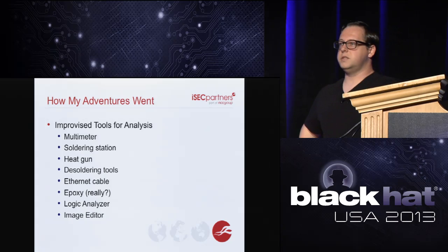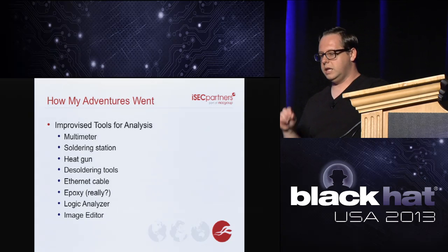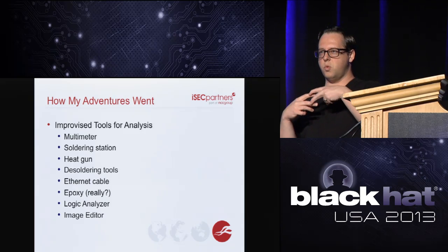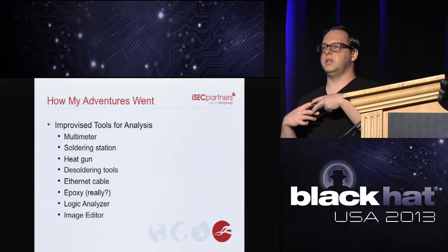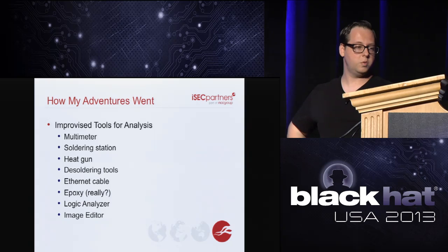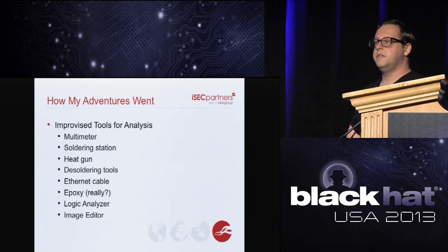The other thing it can do is, if you have really small leads and you want to get some wires on there, if you're just right and you put enough pressure on, you can push the wires on and glue them together. So you can actually glue the wires with epoxy directly to the leads and do some sniffing as well. Logic analyzer: this is crucial for figuring out what's going on on the board, what protocols are being used, and what buses are sending data when.